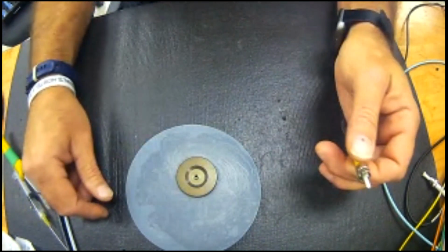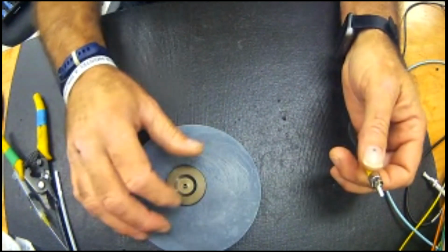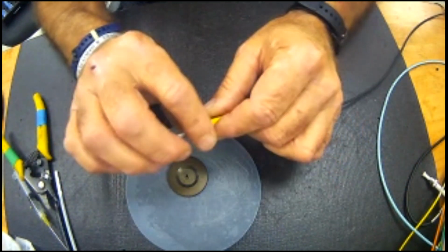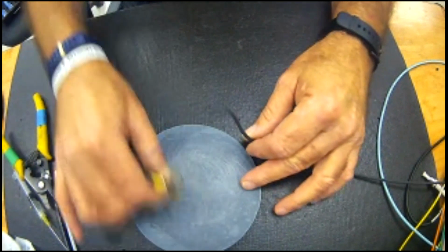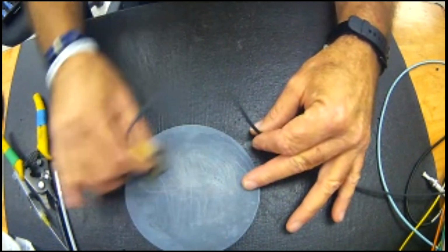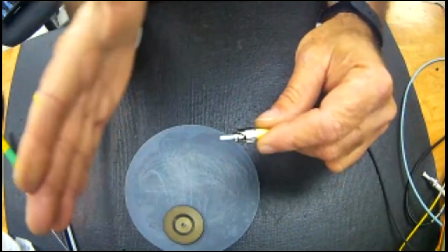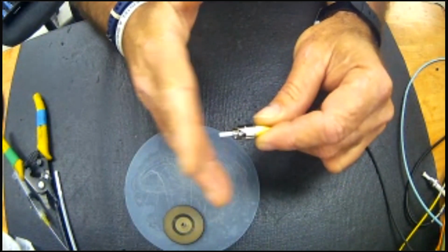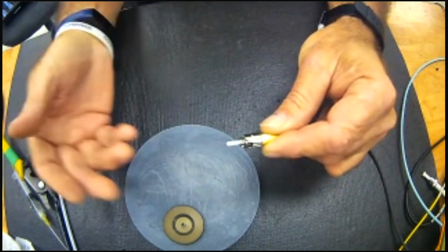You can use a basic puck. This is a universal puck for 2.5 millimeter, which is the diameter of that ferrule. And I'm going to quickly do some figure eights, 8 to 10 passes, and voila, I have reduced the epoxy and the glass, the burr on the glass, to the surface of the zirconium.